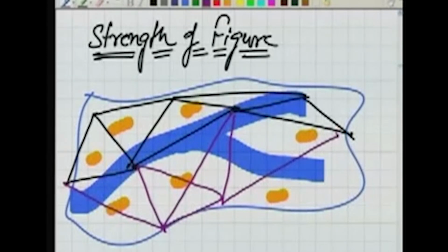So now we have one is this route. See, that's our baseline. If I say A, B, so AB is the base length which has been measured. Starting from this AB, I want to establish these control networks. So what I am doing, I am computing all these lengths using the angles which are measured inside, all these angles, and then finally I can compute these lengths also.